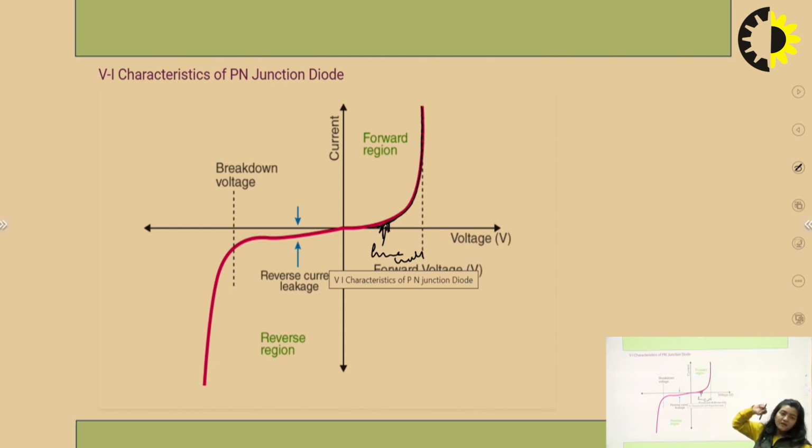As soon as reverse biasing is done, there is some potential difference, but as you apply more and more negative voltage, there is a point at which PN junction breakdown occurs. There is an abrupt flow of current, and no potential barrier is maintained in the PN junction, and the diode is damaged or heated up.